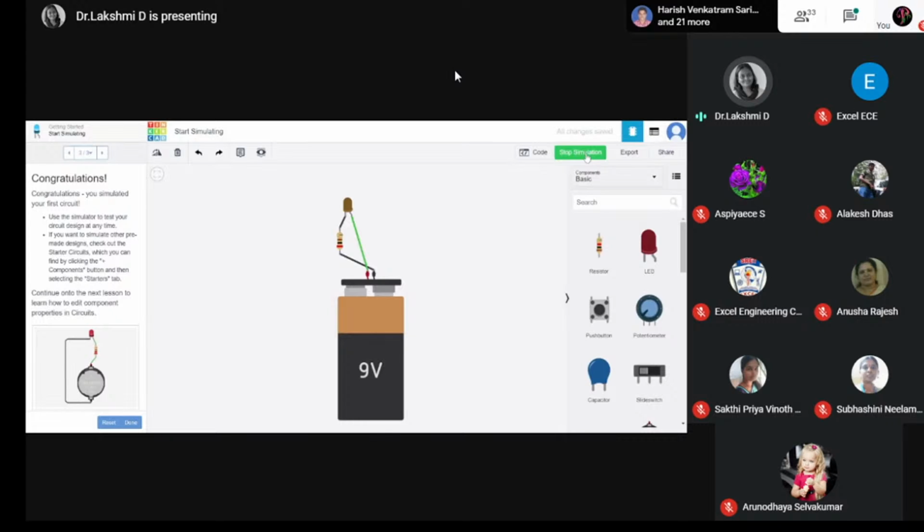Next we need to do digitalWrite. How do we want to write? Normally it will be low. So we need to write digitalWrite of 13th pin, comma HIGH. From low to high, this is the syntax. Low to high we need to activate. Only then we feel that it is working. So some delay, otherwise humans cannot notice it. It will be faster. This is 1 millisecond. If you want, you can set it to 500 also, choice is yours. Next I can make it low. If I do low, a rapid blinking will happen. So this is a minimal code. Let me do it.